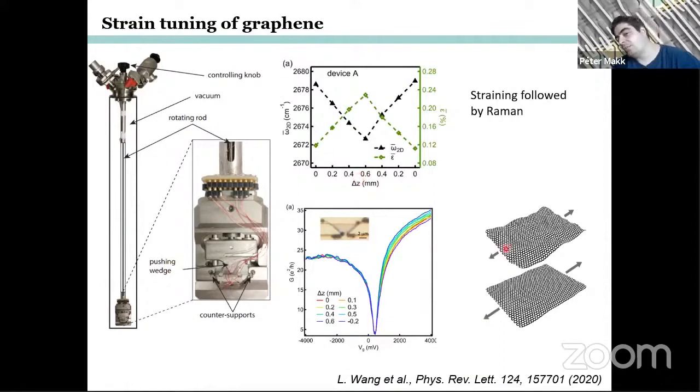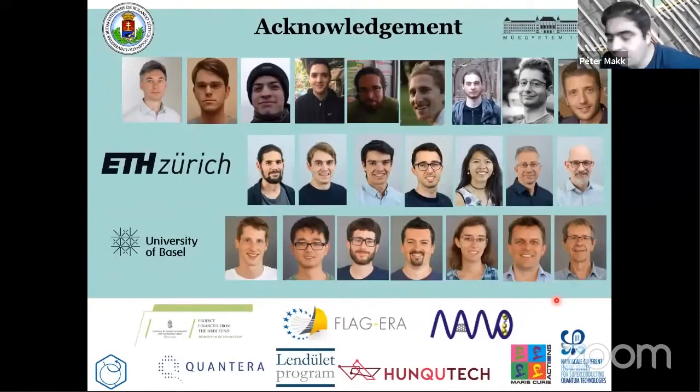One thing which I think can be relevant also for graphene superlattices is that we found that with straining, we can increase the mobility of graphene heterostructures, quite substantially, in this case a factor of almost 2. Via some studies, we have attributed this to reducing out of plane strain fluctuations in graphene, so to flattening out graphene. With this, I think my time is more or less up.